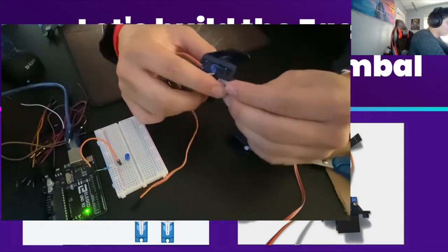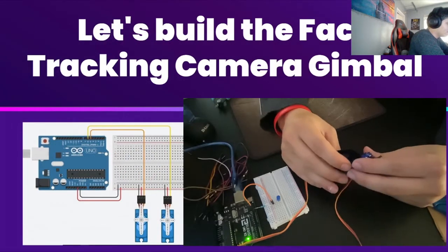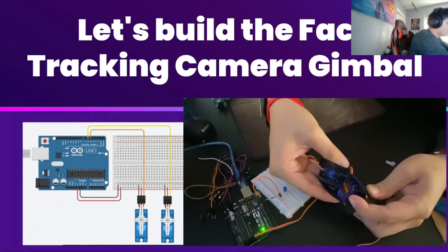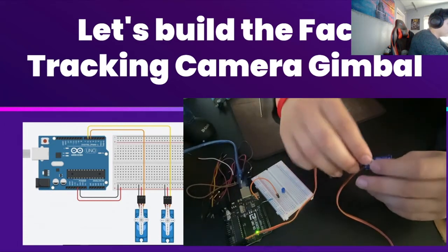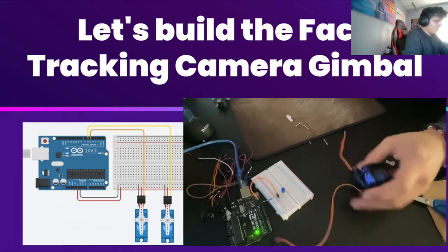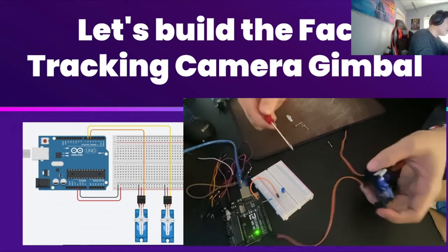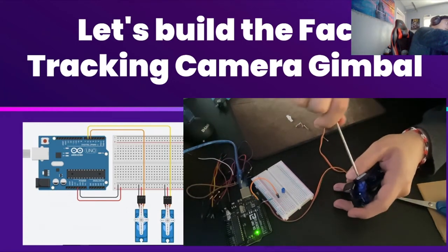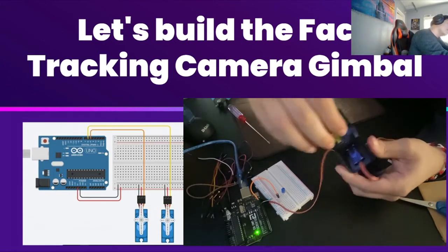So now let's put that in there. We have the servo angled correctly, and let's go ahead and put that through there, and then also right here push this a little bit, and this should help you push that in there. Again, make sure to connect the servo part to the wingtip. And now to ensure that that wingtip stays there, we're going to get the other small screw that came inside the servo baggie, and we're going to put that on the side right there. So that won't move. And now we have our gimbal.